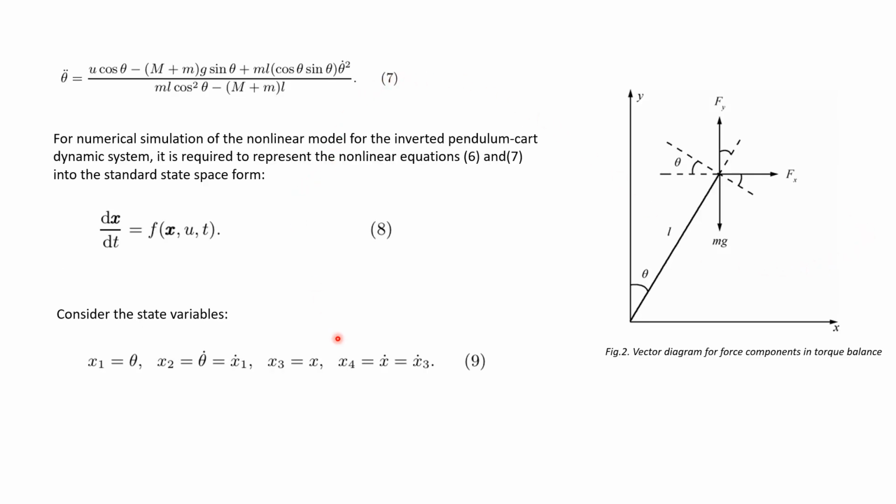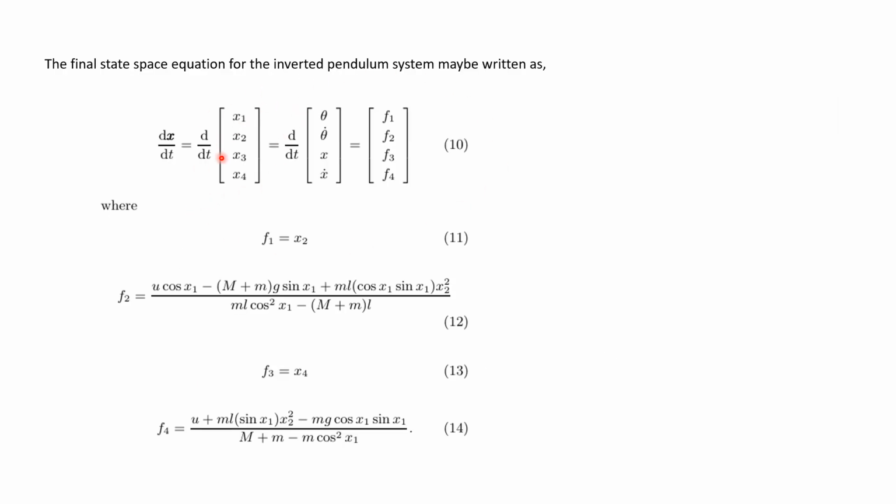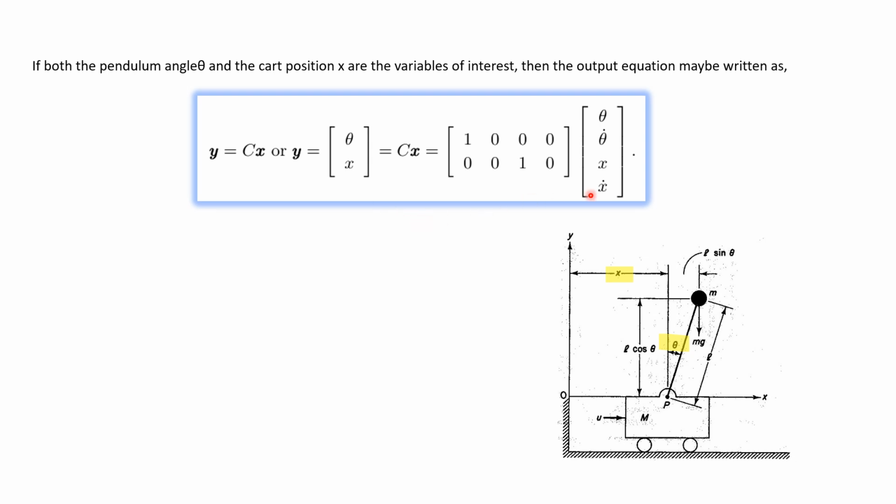Finally, I convert these into a state space model, which is essential for the controllers. We are focusing mainly on x and theta, where x is the cart displacement and theta is the angle of the rotation.